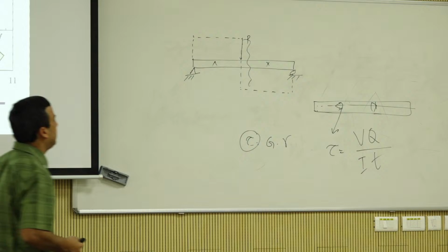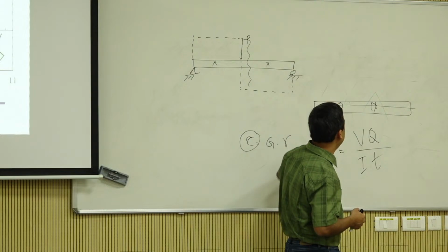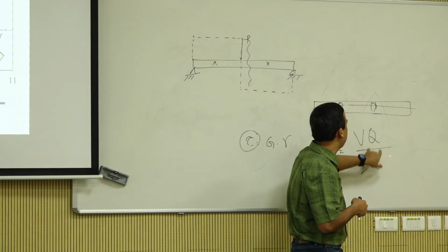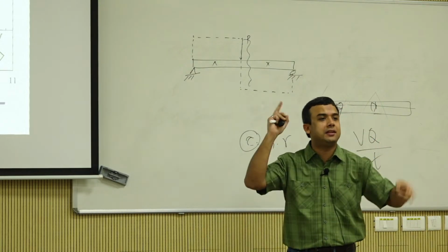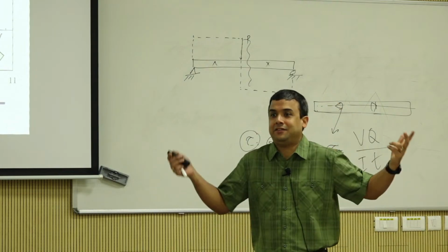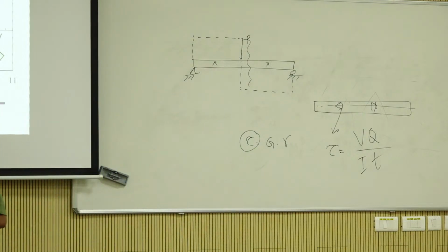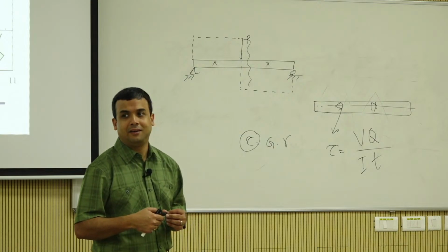So the idea is, if you are able to measure shear principal strain, calculate the shear strain, shear modulus is constant, then if you multiply, because the material properties are constant, then you know the shear force at any point. And if you have 2 points, you know the shear force, you take the difference between them, what happens? You know the load. That's your load cell, right? You just install it on the rail, and then as the train is going, you get your wheel loads, right? Fundamental second semester mechanics of solids application, right?